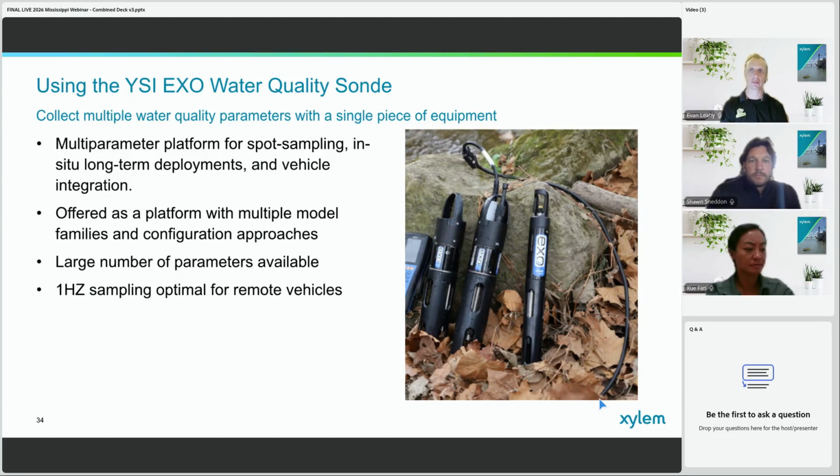Yeah. Briefly, there's an arming feature on there, so that you can have it in an armed and disarmed state, which makes it easy and safe to carry in a disarmed state while the boat can be turned on. Where you arm the vessel is the location the vessel will return to on either a low battery alarm or loss of comms between the boat and the transmitter.